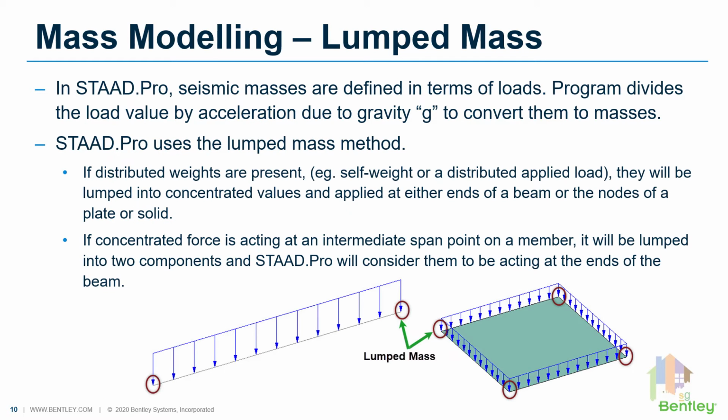STAAD works with the lumped mass principle. That means whatever load you have applied on your structure as seismic weight, during analysis, that load is converted into lumped mass. So if you apply a distributed load, like a member load or a self-weight of a member, the overall force is calculated and that force is lumped into the end nodes of a member, plate or solid element.